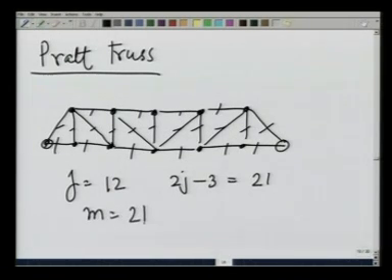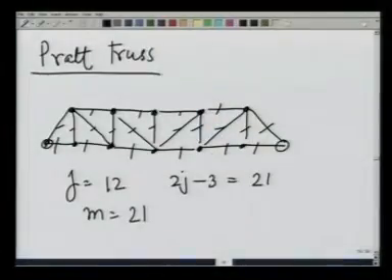So, this is a statically determinate truss and capable of remaining in equilibrium. These points can be fixed. On the other side, either I can have a fixed pin, or usually you put it on a wheel. I will comment on this a little later. Let us look at some other trusses in the meantime.